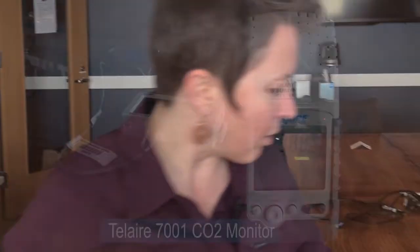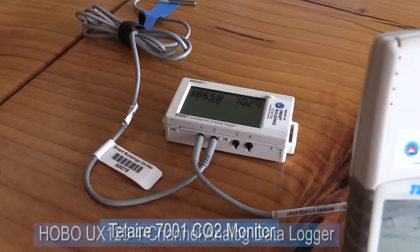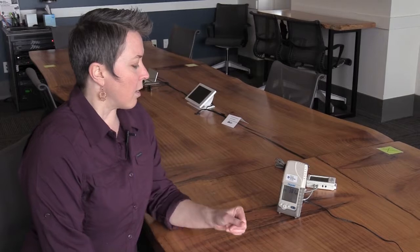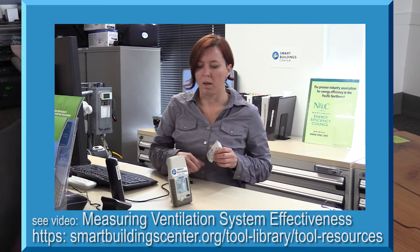So we can use that number as an indirect way to estimate how much fresh air we're bringing into a space. So here I have set up a Telaire 7001 CO2 monitor, and it is attached to a HOBO 4-channel analog data logger, which is logging the data. And in another video called Verifying Ventilation System Effectiveness, we go into detail about how to configure these loggers.